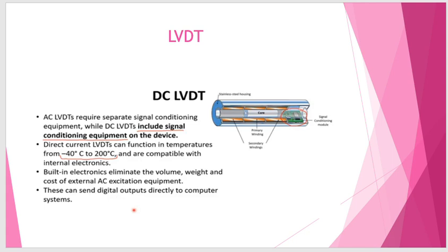It offers efficient operation and is also sensitive, meaning even small changes in displacement will show changes in output. You can use an amplifier here, and the hysteresis loss is usually lower because in the moving assembly there is no friction like in other types. It means lower power consumption and it converts displacement directly into electrical signals, so we get the output pretty quickly. Those are the advantages of LVDT.